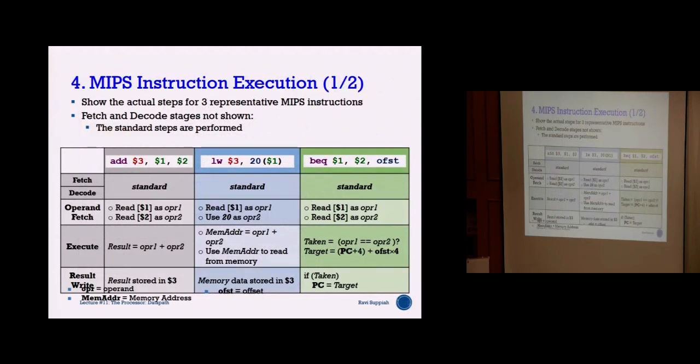Okay, so let's understand a bit about how this is going to play out here. These are all the cycles here: fetch, decode, execute, and write back. Fetch and decode, we already know what it is, because fetch means you take the address, send it to the address bus, and your memory will reply back with the instruction in that address. So that is your fetch.